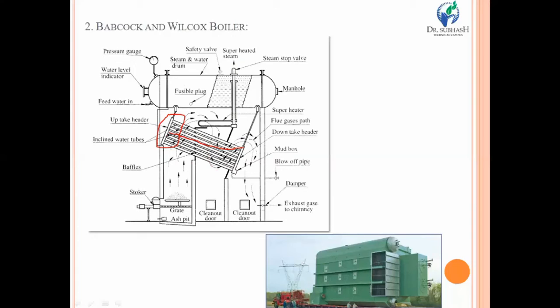So in order to remove those water droplets from the steam, the steam from the outlet of the evaporator will be stored first here, and it will be recirculated once again through this tube. Particularly, this is the superheater. Once again there is a heat transfer, and now the steam absorbs fresh heat coming from the fresh charge of flue gases, and this time the wet vapor steam is converted into superheated steam at the end. So over here you find the steam has a superheated condition.